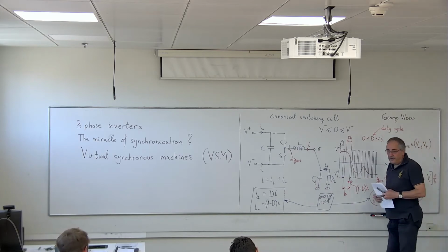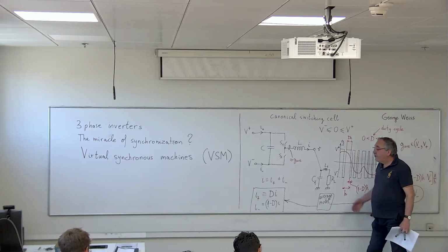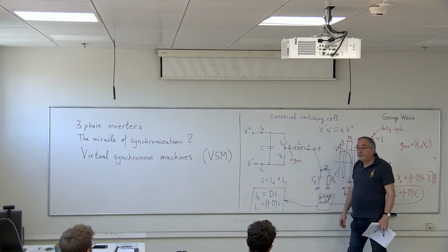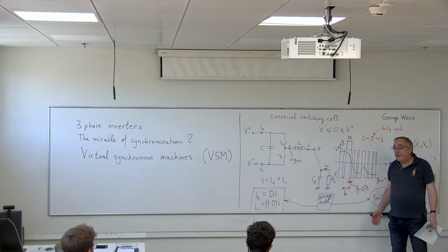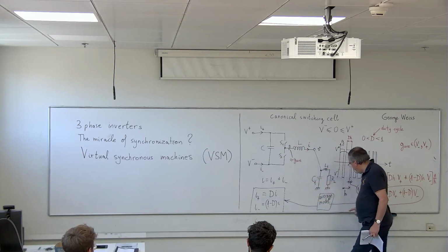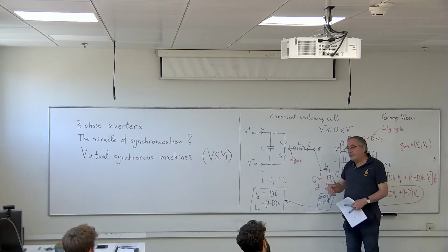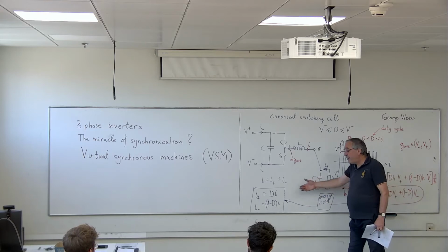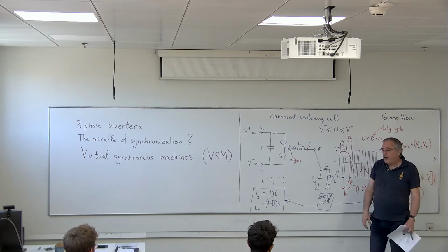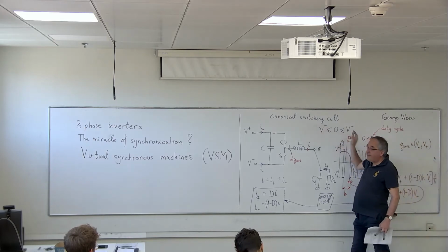When you do simulations of a switch power converter, you have in this converter several instances of such a canonical switching cell, and you don't want your simulation to run for days. Then you replace the exact model of the canonical switching cell with this average model, which is a very good approximation, and the simulation will run much faster. And you will see the results will be, of course, much smoother because you have removed the high frequency oscillation. Now, this was the preliminary about what is a canonical switching cell.